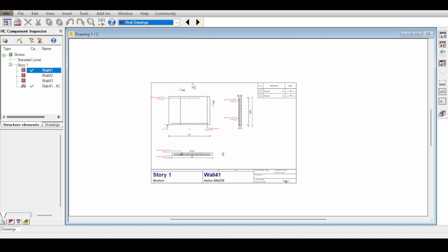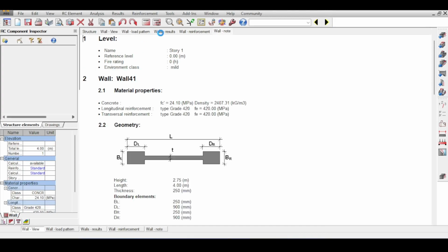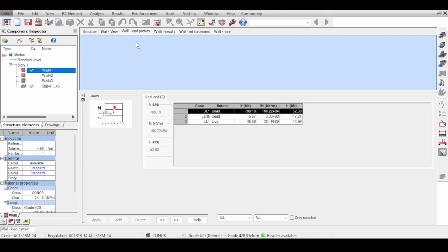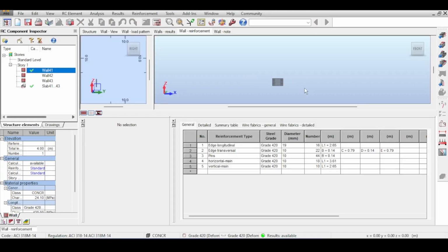The reason why it's useless is because it's based on a totally bogus assumption. The assumption here in the load wall pattern is that there are no perpendicular loads on the wall, and it doesn't see the MXX and MYY moments at all. And that's the reason why this is absolutely unacceptable. And even if the program tells you everything is fine, you should not trust it.